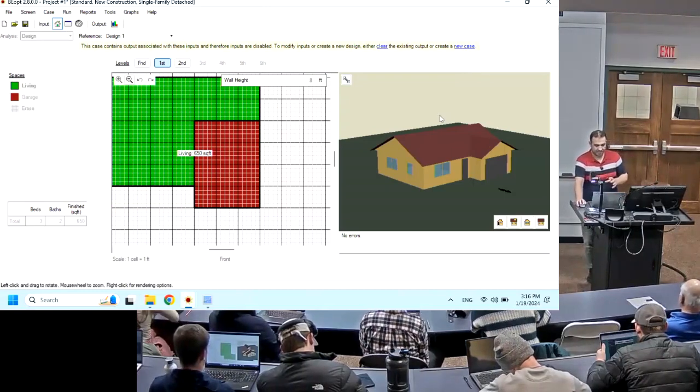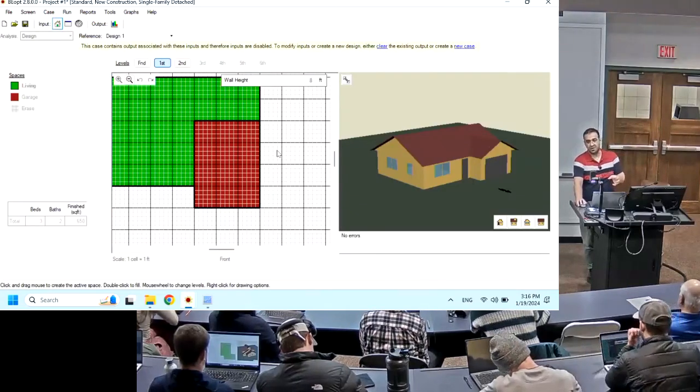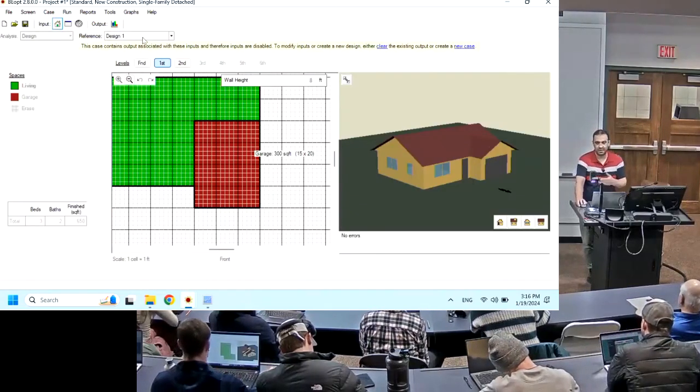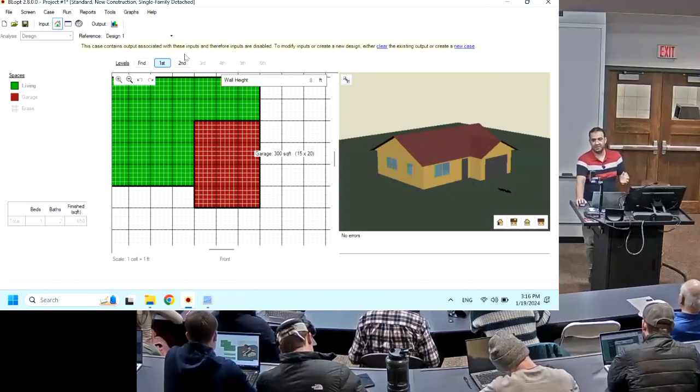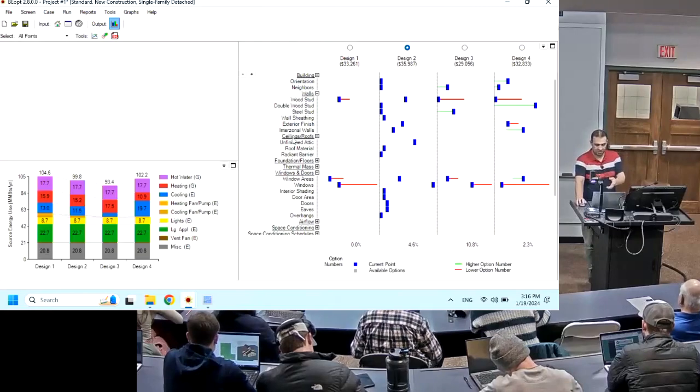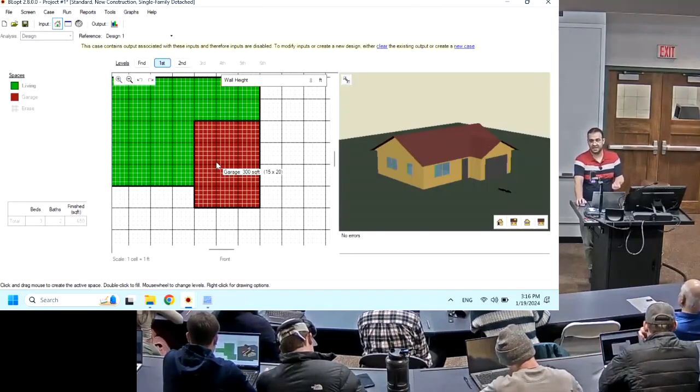The reason is that it could happen that you run a simulation, you have your result here, and then you go and change your model and save your file without running the simulation. So when you later open your file, you think that those results were for this model, but that's not the case.